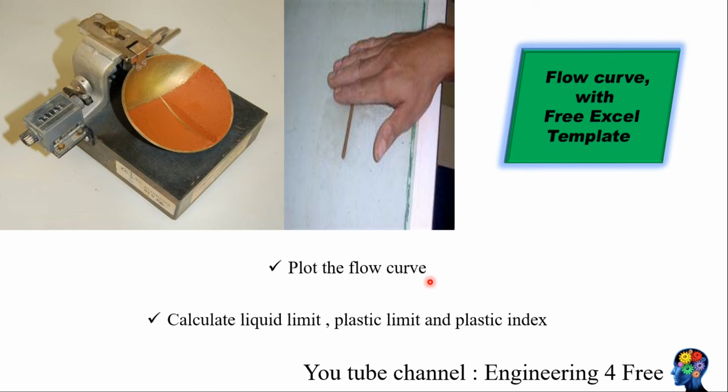As you remember from your previous courses, the property of fine-grained soils depends on mineralogy but also on moisture content. Fine-grained soil properties change radically in the presence of moisture. We can calculate these changes and see how they affect the soils using Atterberg limits.